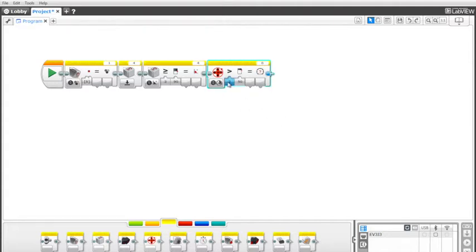If you run your motor at 50, whenever the current power is less than 45, you can use this condition to detect if the motor stalled because of a bump or something. Whenever it's bumped, the motor stops turning, then the power eventually drops below 50, the condition will be true, and then you can do something based on that.